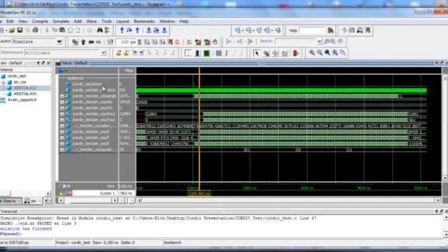And you'll notice there's the start signal that I talked about. The clock, I'll zoom in so you can see it better. The input angle, which is going to step in 1 degree increments every clock cycle. So we're changing the input every clock cycle because we've pipelined the architecture for the quartic. And then the xn, now remember it was 32,000 divided by the 1.647 system gain. That gives you this value here. And notice at the appropriate time, the x out for the angle is going to be right at 32,000. This error is very small.